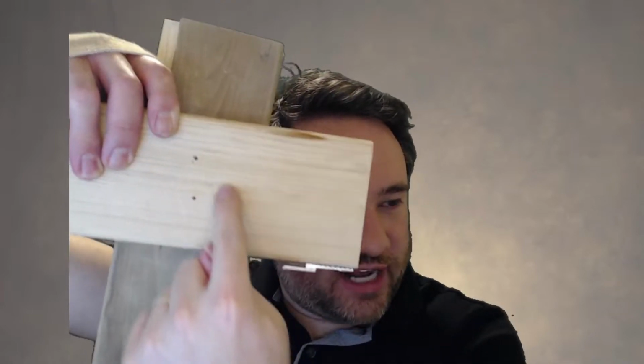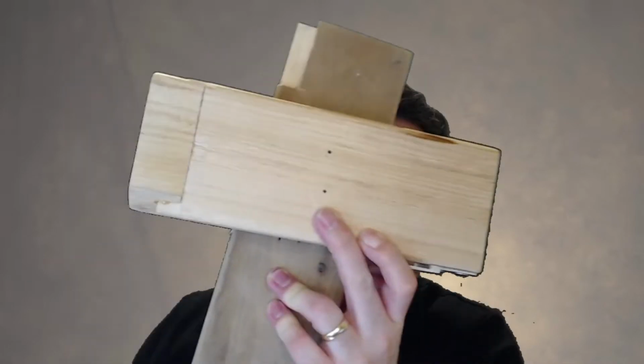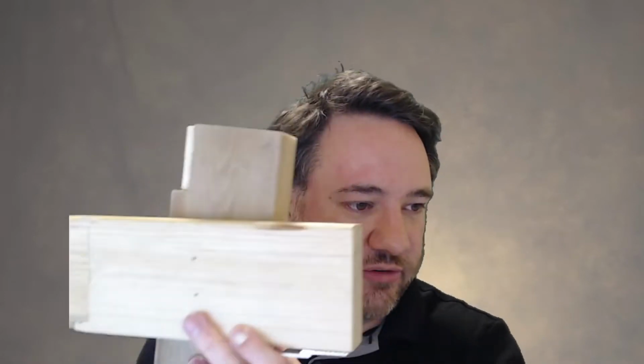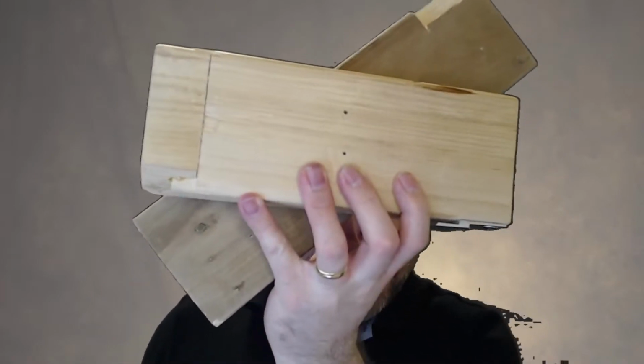when I calculate how far apart these nails have to be, which is going to be basically the parallel to grain direction spacing, which is more stringent than the perpendicular grain direction spacing, as we talked about for the reasons that we talked about. Okay, when I have things on an angle, it's a little bit more complicated, but there's a very nice figure in the standard that tells you exactly what to do. So I'm going to take a look basically at the case where we have two members connected perpendicular to each other.